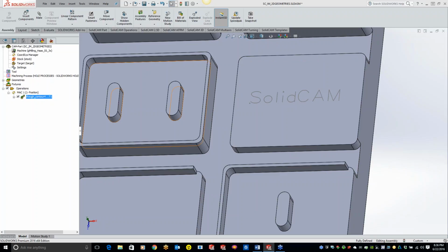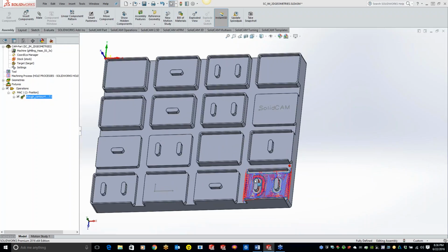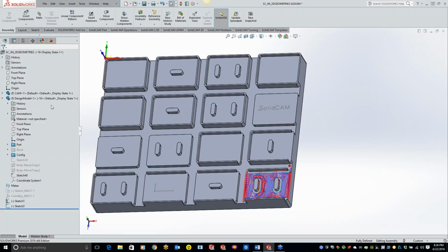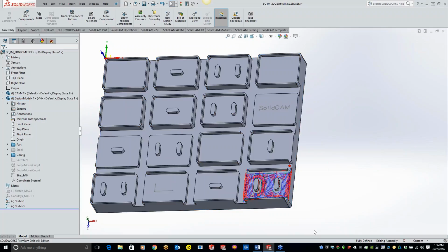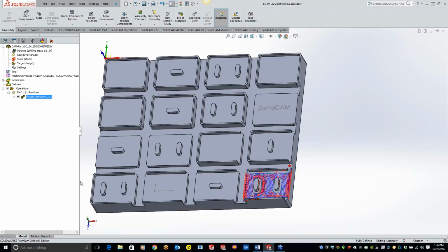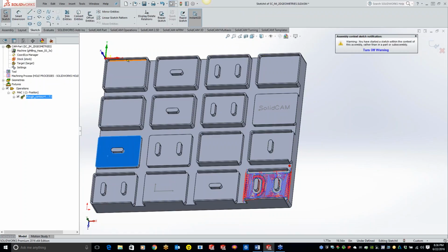Does it matter if the geometry is created on the CAM or the design model? No, Ronnie, it does not matter where it is created. When I create those sketches, like that little L sketch, if I come over to my SolidWorks, you just see it added it below as an assembly sketch. So it's not reflecting back to anything in here. But if you wanted to, you can edit this model and draw the sketch that way too. But just to save time, you're already in your SolidCAM program, and you can just right-click, do the sketch, and do your sketching right there.